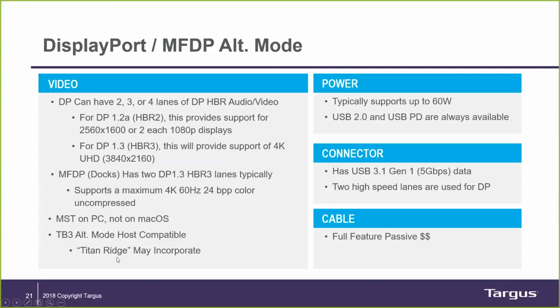Now that will change. There are implementations of the new Intel chipset for Thunderbolt called Titan Ridge. There are implementations that will change. And therein lies another bit of confusion, because now that you can connect a DisplayPort host to a theoretically Thunderbolt dock, it'll work in DisplayPort mode with the new Titan chipset on some designs. It doesn't mean that it still works on every Type-C port. So don't be confused by that. Don't be fooled by the marketing hype. It's a more compatible version of the Type-C implementation of Thunderbolt and DisplayPort, but it isn't universal yet.